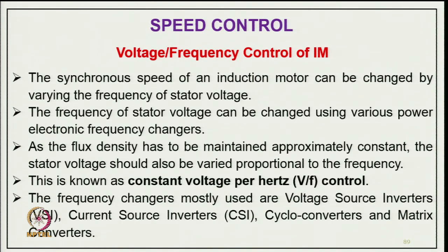When you change the frequency, of course, the synchronous speed is changed, and this is considered one of the best methods for speed control by variable frequency drive. Nowadays, we have solid state drives for that purpose. Anyway, you can have regeneration in many applications like railways and metros, all of which now use variable frequency induction motor drives.